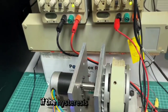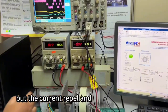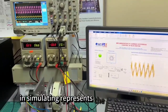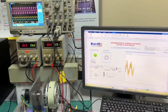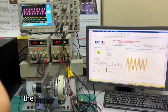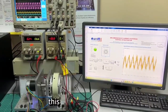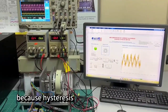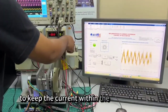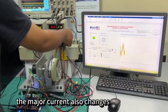If the hysteresis band is too large, the switching frequency will become lower, but the current ripple and torque ripple may increase. The waveform shown in Simulink represents the comparison between the reference current and the measured phase current. Based on the experimental waveform, the motor current is able to follow the reference current with some ripple. This ripple is expected because hysteresis current control uses an on-off switching method to keep the current within the hysteresis band. When the reference current is adjusted, the measured current also changes accordingly.